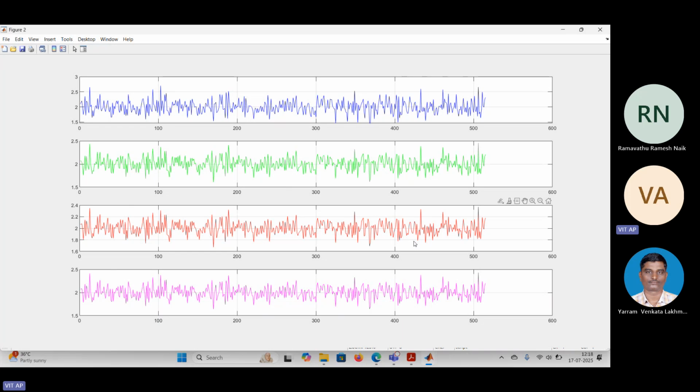You can check this in all three or four scenarios: the average power is the same. The first plot is without companding, the remaining three are companding. So irrespective of the modulation technique or the companding you apply, the average power remains the same. We get that by doing normalization for companding. If the average power remains the same, then we are eligible to find the bit error rate. Now we can check the peak values.